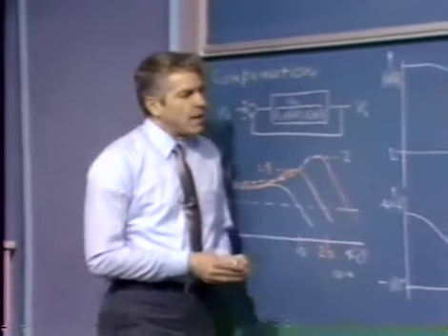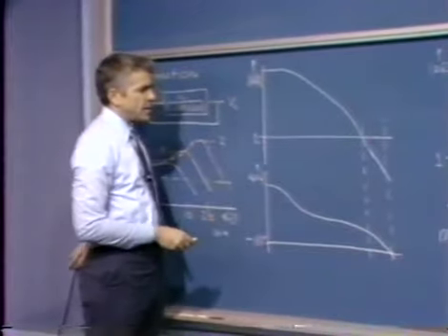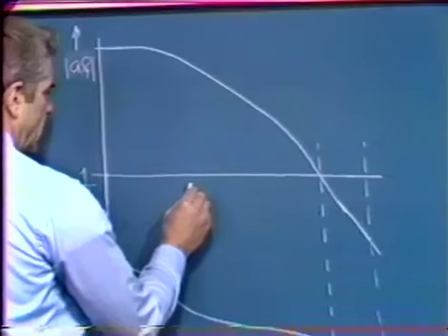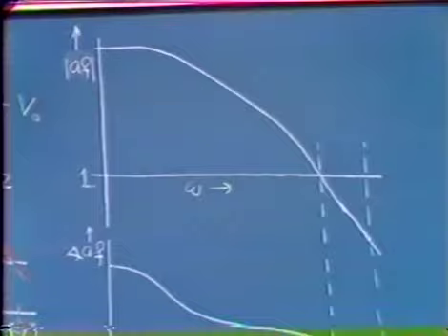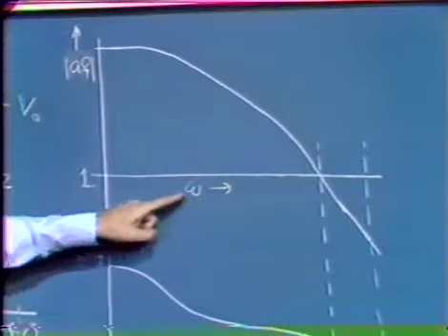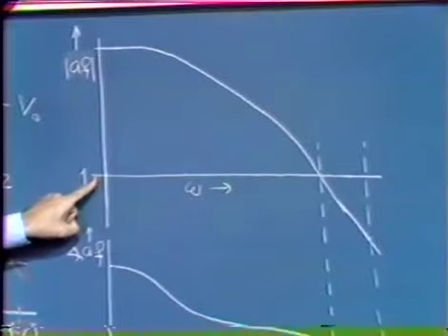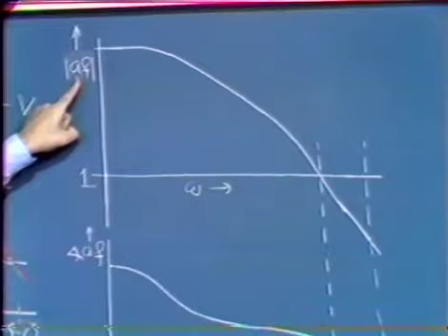Here we have what might be a sort of typical AF product Bode plot. We're running, of course, on a common frequency scale here, so omega goes in this direction. These are the usual Bode plot coordinates, a logarithmic axis for frequency, a logarithmic axis for magnitude. Here's the magnitude of the AF product equal to 1. We're evaluating AF of j omega.